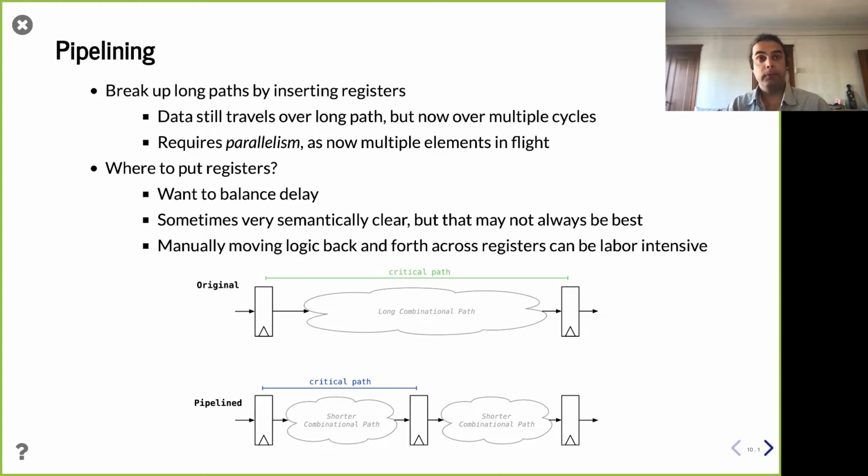If you look at perhaps the future of hardware design, which is not just things like Chisel, but things one level up, perhaps like HLS, you can see one of the things HLS does is it tries to free design from thinking about things in terms of time semantics. So Chisel is a very productive language, but at the end of the day, when you're writing Chisel, you are thinking about exact time semantics. Like this particular operation happens on this cycle. This operation happens on this cycle. And I want a wire here and a gate there. And I want a register here, right?